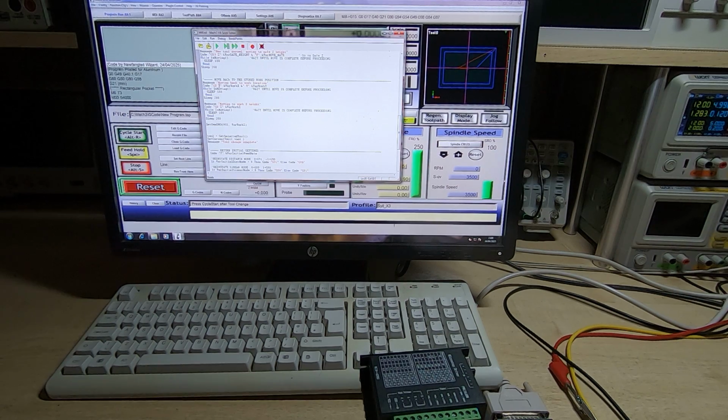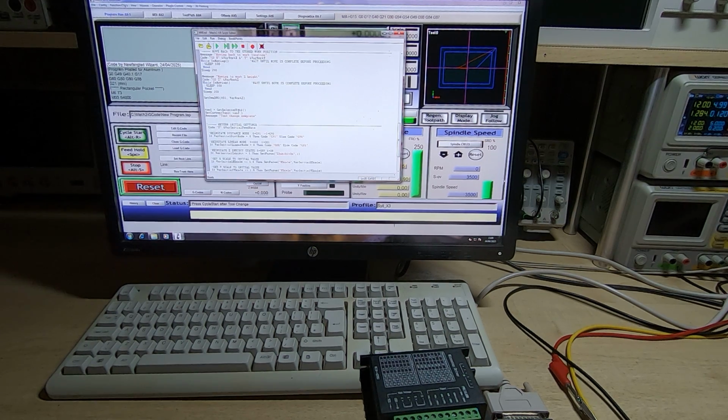It moves back to the work start position. That's the X and Y that we saved in the first macro, and then it moves the Z axis down to the start Z position. Now remember, this is the G54 fixture offset that we're working in, and this is the one we've just updated, so it's not going to move the quill or the milling head down to the same location. It's going to move the tool tip, the new tool tip, down to this location, which is exactly what we want. Once it's done that, it completes changing the tool.